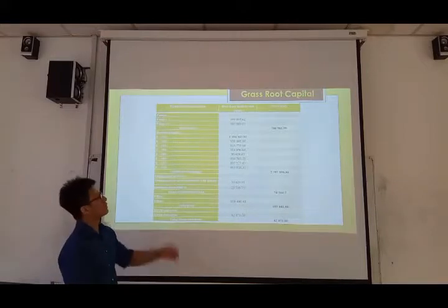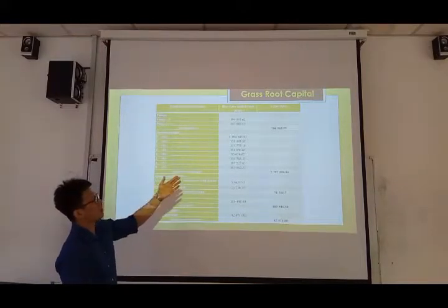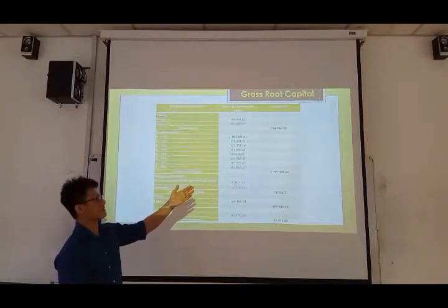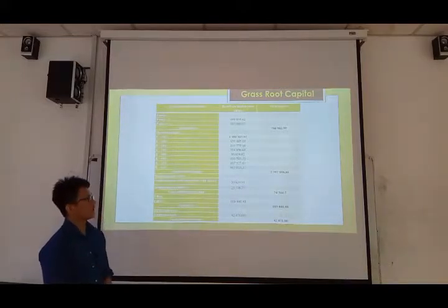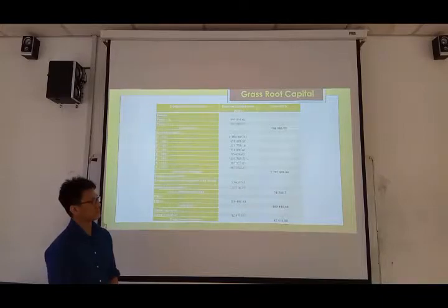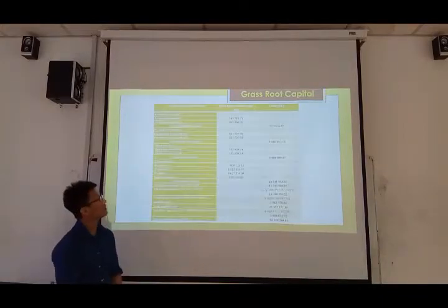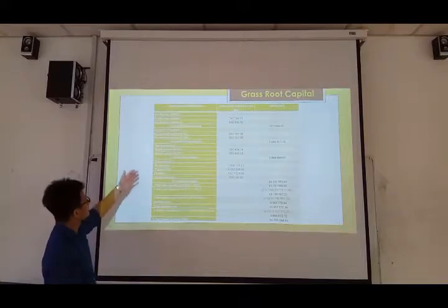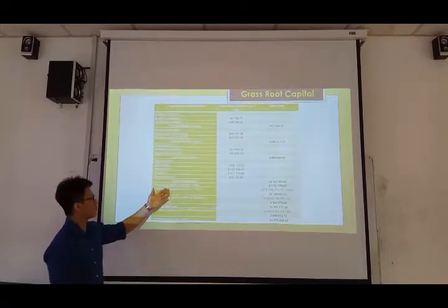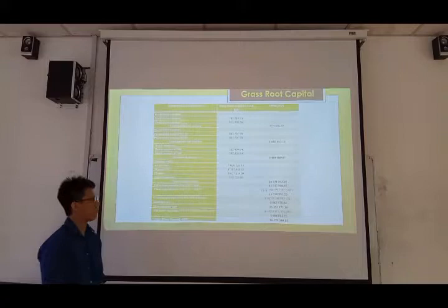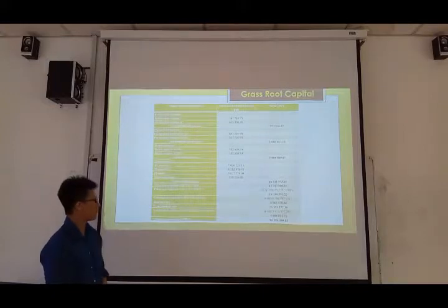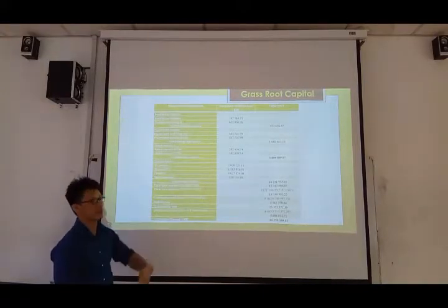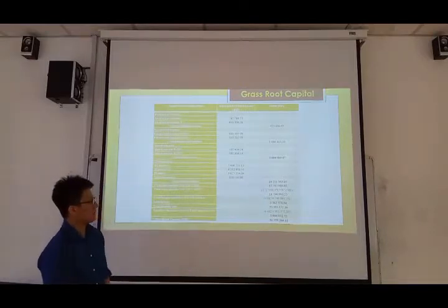So for example, the total base bare module cost for total pumps worth about 766,000. For total heat exchanger, it worth approximately 2.8 million, and so on. So the equipment list continues. The total bare module cost based on CE index in 2004 is around 17 million, and the total bare module cost based on CE index in current year, which is 2017, is approximately 20 million.